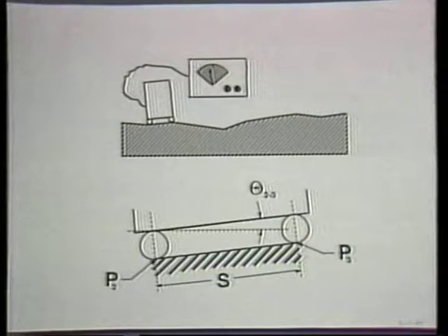The measurement device is now carefully positioned at the second position. That is, the rear foot of the device is now precisely placed where the front foot was located in the first position. The tilt reading for this second segment is recorded. In this manner, the measurement device is stepped through each of the measurement positions and tilt values are recorded for each of the path segments.